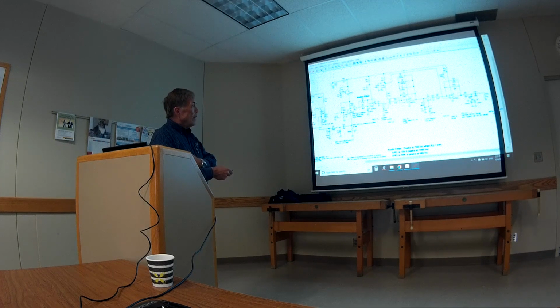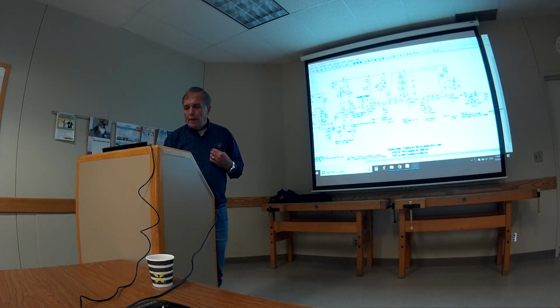Here's the volume control. I should have two split resistors. I set them fixed at about the maximum right now. And then I get to this first audio amplifier. By the way, the audio filter got a gain of 1.3 already. It's not meant to be amplified. This one gets a gain of 35, which is 31 dB. This one gets a gain of 32, which is 30 dB. And this is just a little mute circuit in here. It's commonly used. You ground this and it'll shut off the flow across J1.